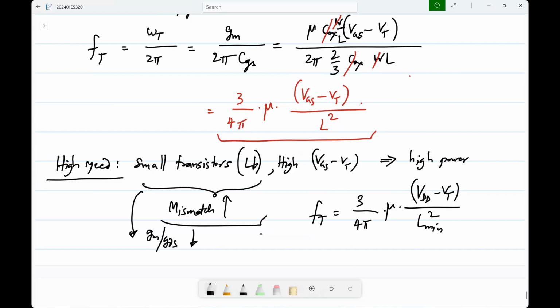If you remember the expression for signal to noise, it was proportional to the bandwidth, and the expression for the power dissipation was proportional to the product of bandwidth and signal to noise ratio. So for a given bandwidth, you increase the power dissipation, you will increase the signal to noise. Here we are talking about increasing the bandwidth, right?